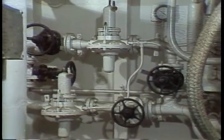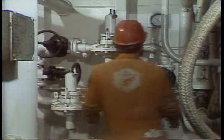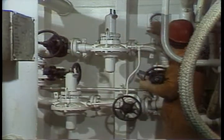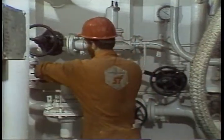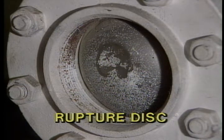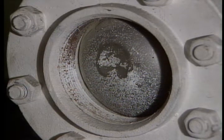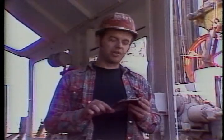Some people have been known to readjust the regulator in the air supply to increase the pressure, thinking they'll blow the plug out. They may blow the plug out, but they'll also blow the rupture disc out too. The rupture disc is this little device that ruptures when your operational pressure exceeds the rated pressure of the system. This is a rupture disc. It is designed to rupture at 39 psi. In each of our 8 P tanks, we have one of these rupture discs inserted.